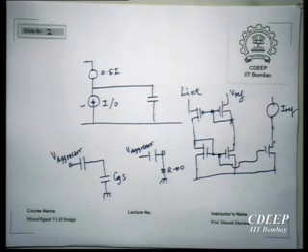So that is the great advantage here. Each line, as far as voltage is concerned, is just sleeping at a fixed voltage and is neither receiving noise nor giving out noise. So it is like a punch shield. No real aggressors, no real victims. That is the great thing about this. So overall noise is low and therefore you can afford to have delta V's which are much smaller. Hence either use I's which are much smaller or both I small, R small.